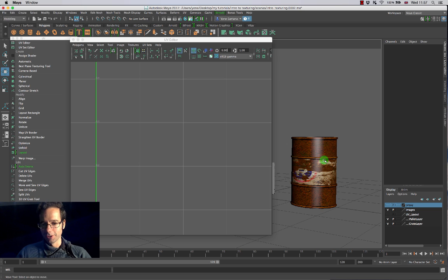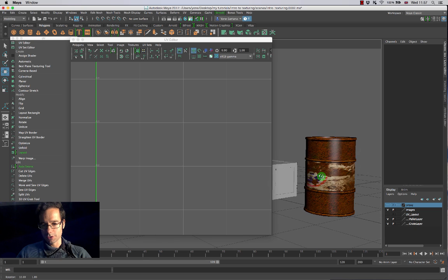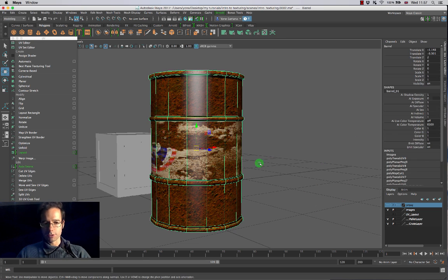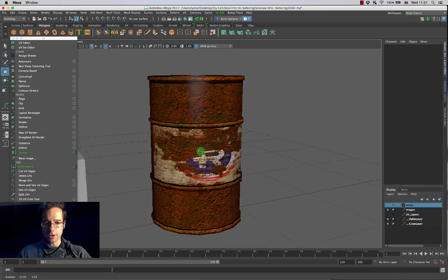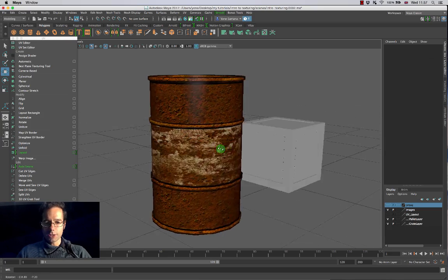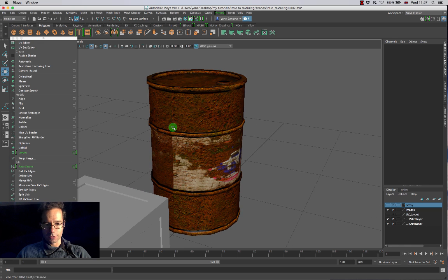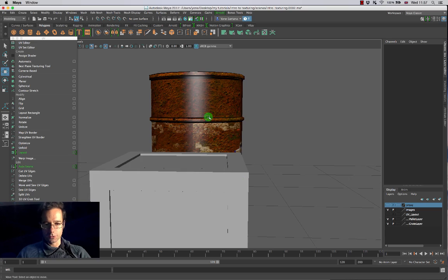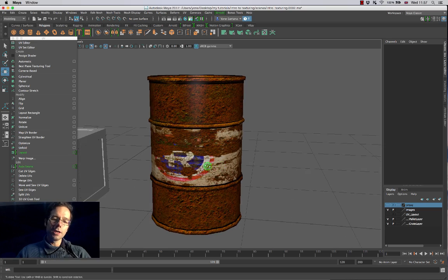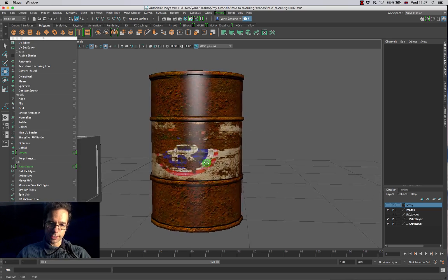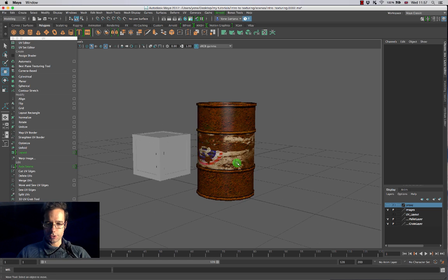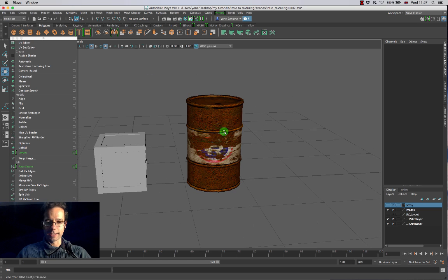Okay, so again, as I come out here, you're going to see that I've got this reflective Phong material with this diffuse texture of this oil drum, where you can see a little bit of the glint inside of the highlight. I'm just going to focus on this object for a second, and you should see that here we've got a fairly good representation of this. There's a little bit of a seam over here as well, which I would have to go into Photoshop and fix to make sure that it disappears. But importantly, we can see that we've got a nice little simple texture just by adding, again, the UVs in the correct place.